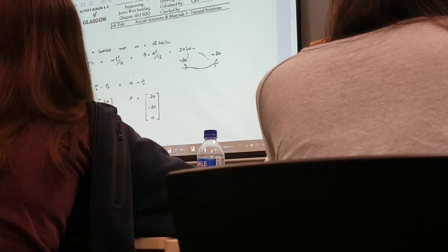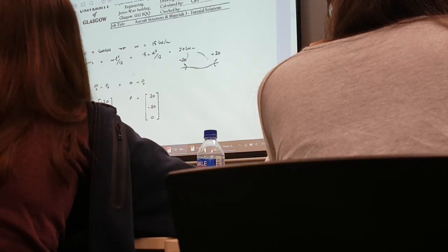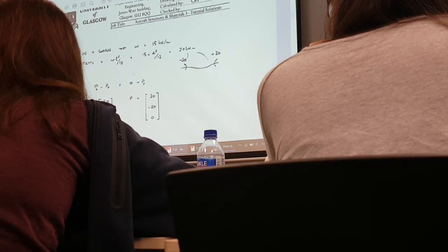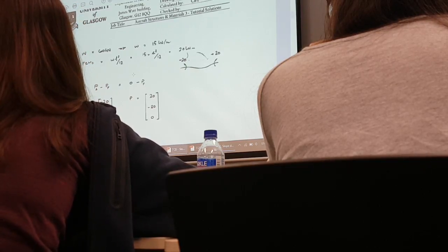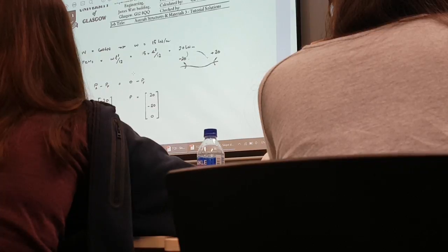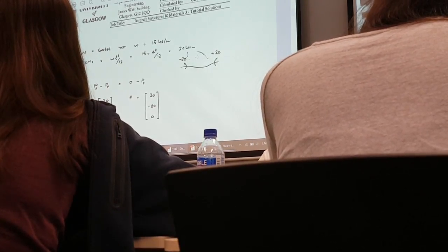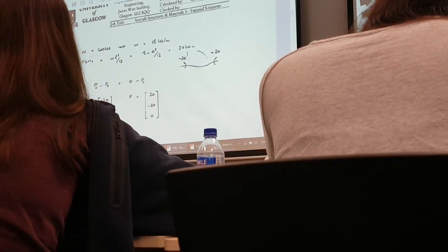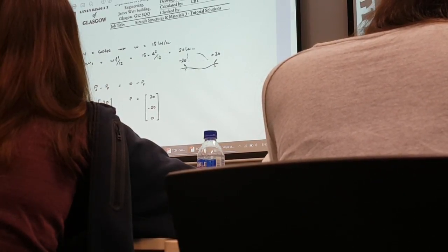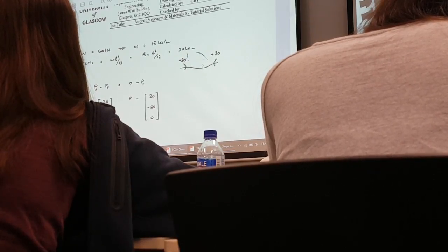As I asked in the earlier part of this question, what is this loading condition? This loading condition is a load between nodes. Once you have a load between nodes, you know that you're going to induce what we call the fixed end moments. That's where the PF comes in. For this case, the uniformly distributed load acts on member BC.